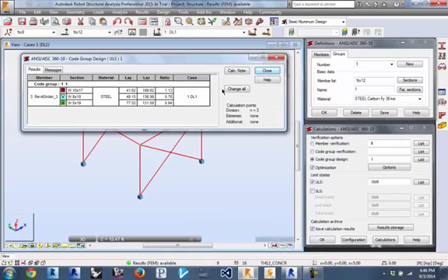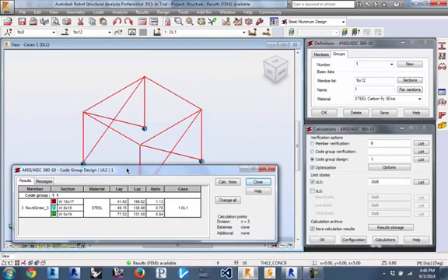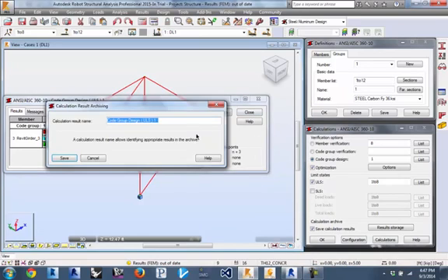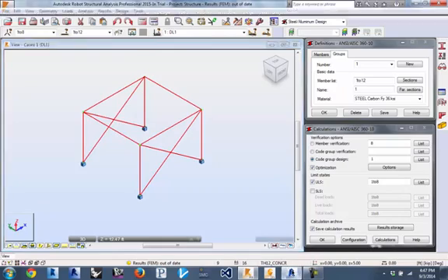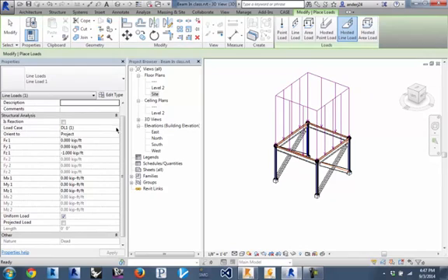So if you put, say, a composite deck floor with the steel and the poured concrete, is that going to automatically associate a dead load, or are you going to have to go through and designate the dead load? When you're doing this in Revit, you would have to go through and designate all those loads. In Revit, if you look at the load types here, you do your dead load, your live load. You can apply wind loads to this, snow loads, and any sort of temporary loads.